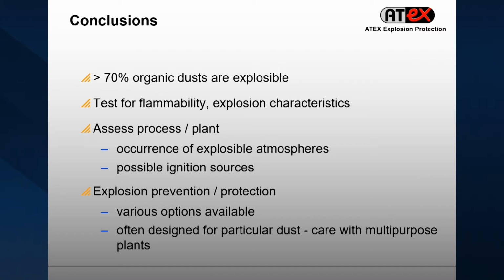So, conclusions for this part, before I give a few other application examples: about 70% of all organic dusts handled are explosible. So you have a good chance that you have explosible dust in your facilities, and that means if you do not have any information about your products, then you have to do some tests for flammability.